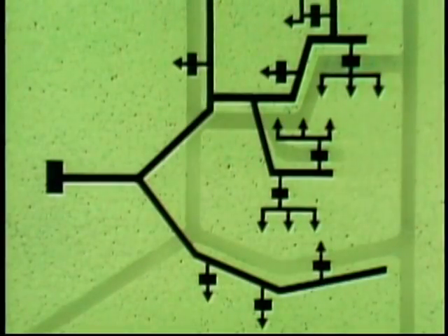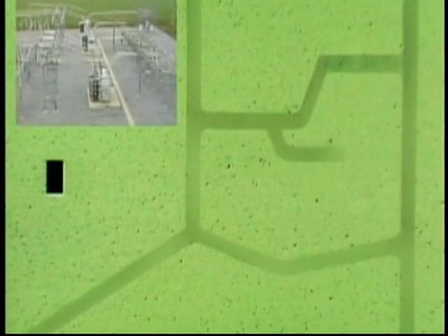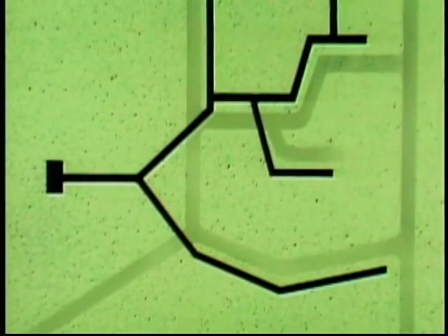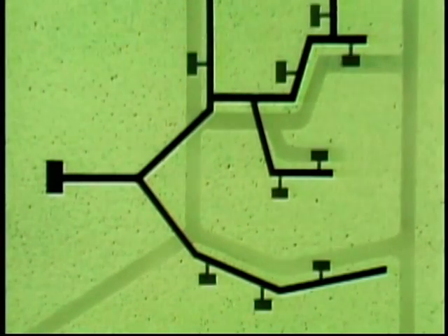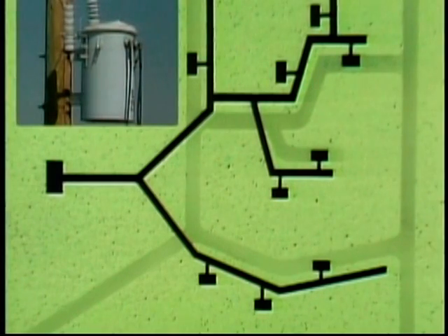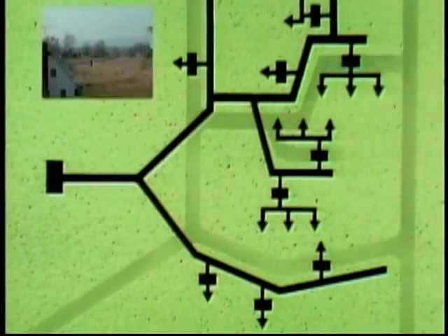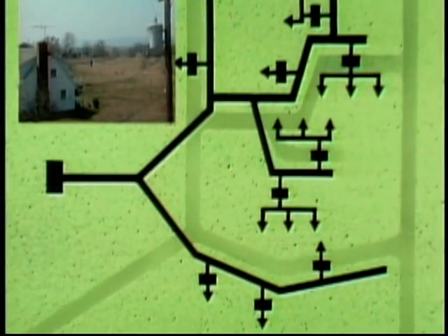A distribution system is the portion of a power system that includes a distribution substation and the components that deliver power from the distribution substation to the customers in the area. The major components include distribution substations, where transmission and subtransmission voltages are stepped down to distribution voltage, the distribution lines which move power to a load area, distribution transformers which step down distribution voltage to user voltage, and the distribution lines which deliver user voltage to the customer.